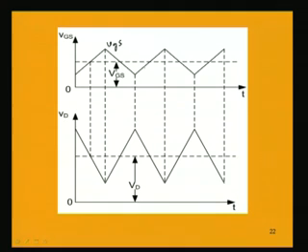So, at any instant, the voltage between gate to source will be found by adding these two, capital VGS and small vgs. So, starting from this DC value, it is rising because we are applying a triangular voltage. It will be rising in this fashion of a triangular wave, rising and then falling. So, this will be the profile of the instantaneous voltage between gate to source.